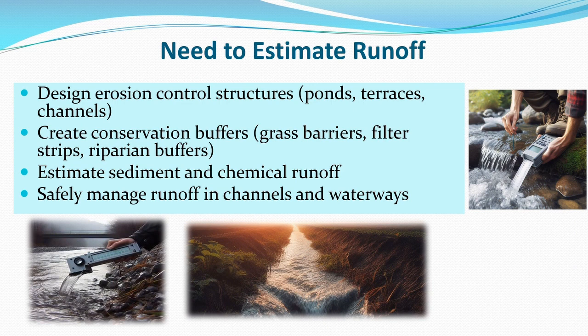Why do we need to estimate runoff? We need to estimate runoff in order to design erosion control structures such as ponds, terraces or channels. In order to create conservation buffers, we need data of runoff. These conservation buffers may include grass barriers, filter strips or riparian buffers.